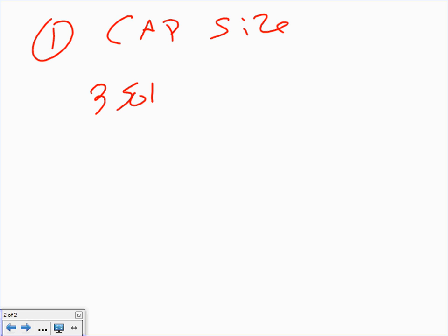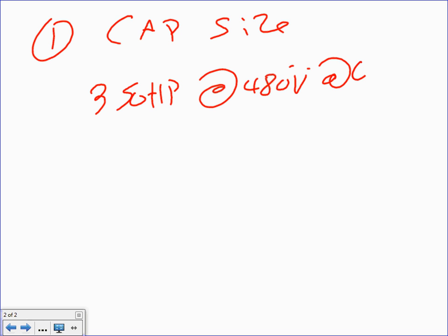So now if you guys look at the sizing, I'm going to take number 1 first. We need to size the capacitor. Capacitor size, standard size. I have 350 horsepower at 480 volt, and at U-frame, and also at, what else? What's the RPM? If I don't give you the RPM, did I give you the RPM for this baby? If I don't give you, what's the most common RPM? 1800. But I will make it clear, the most common one is 1800 RPM.